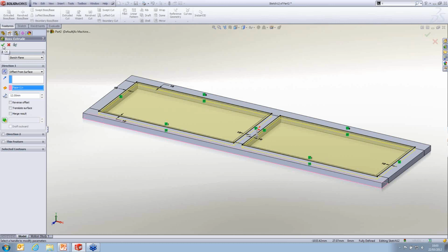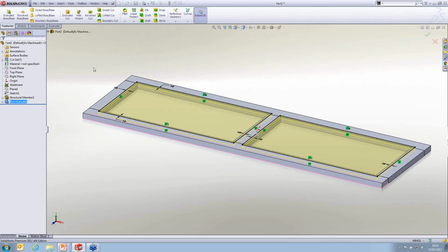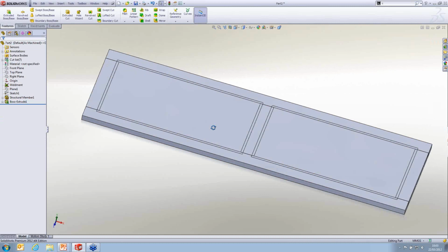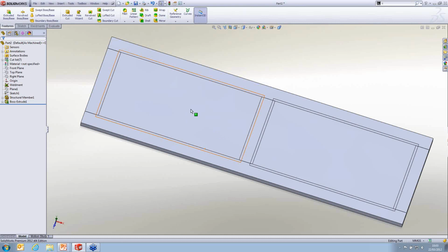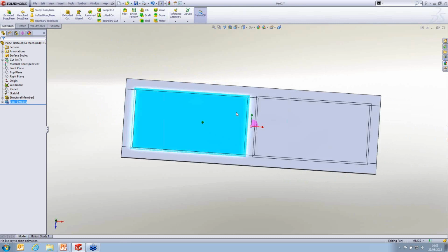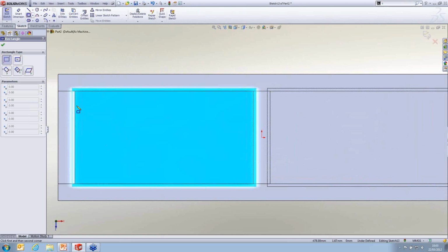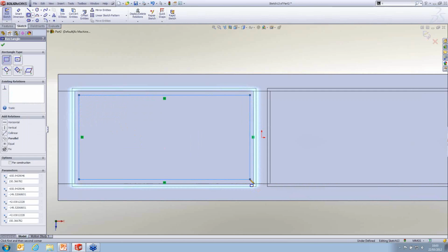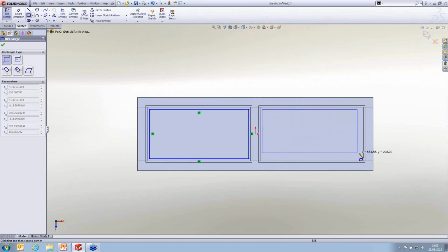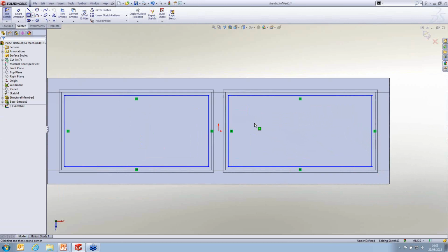So, quite a nice thing that we don't have to toggle off there. So I've added those internal panels on. We actually want a sort of lip running around the inside of the rail, so I'm just going to do that as a simple cut. So we're just going to sketch on this top face, draw those sketches out. Again, we can do both sides at the same time.